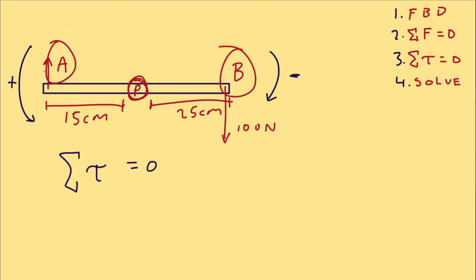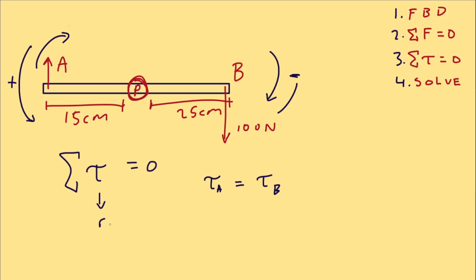Because A and B torque cancel out to 0, equilibrium, then we can write that the torque of our friend, which is counterclockwise by the way, and we'll label this torque of A, should be equal to the torque of our own push, which is going down. And because torque is equal to the lever arm times the force magnitude, then our equation can be expanded into this.